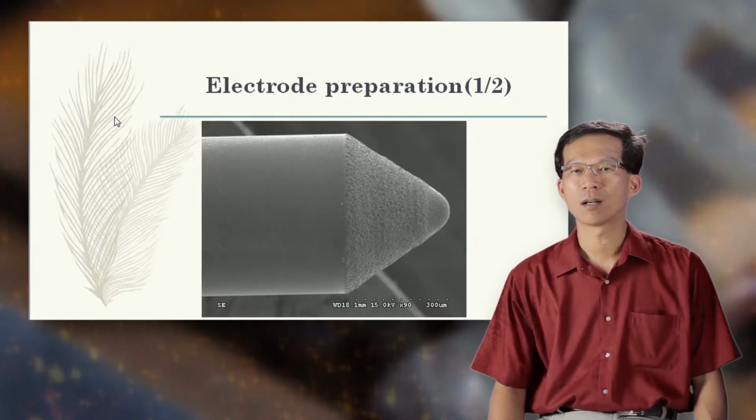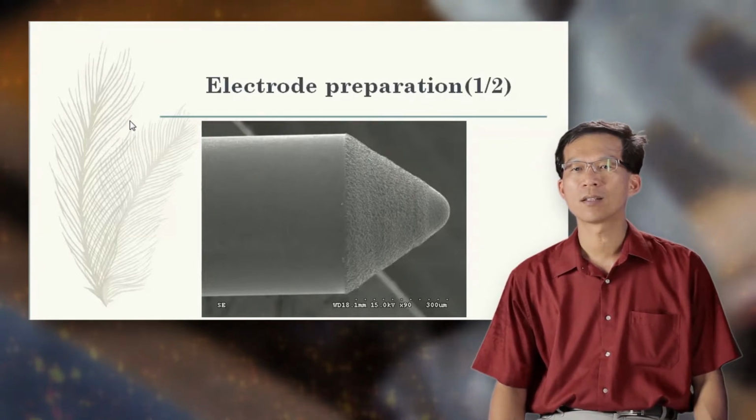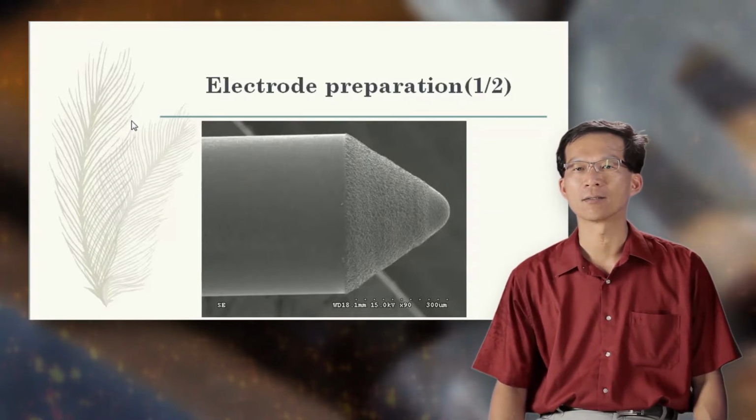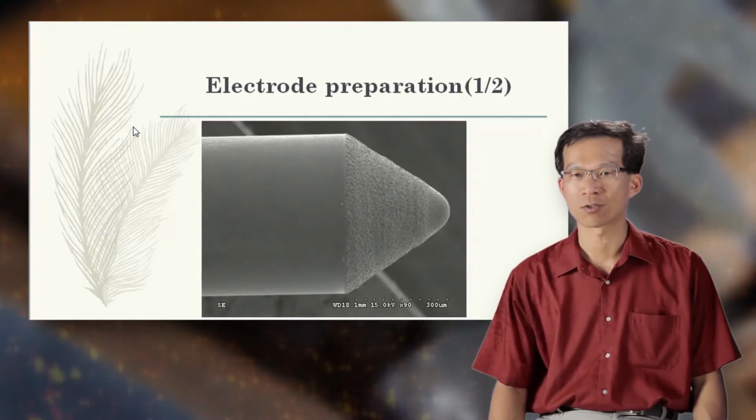The material of the electrode is tungsten carbide. This material possesses very high hardness and leads to low machinability. The radius of the tip is around 30 micrometers, compared to the micro bar at the bottom of this photo. It is not easy to achieve this scale for this material, but it does not cause any problem for wire electrode discharge grinding.